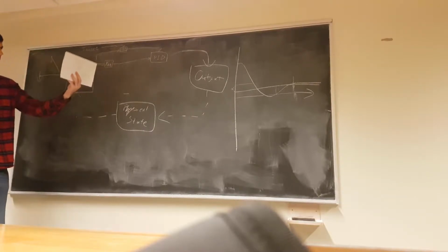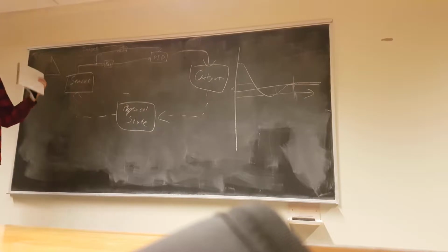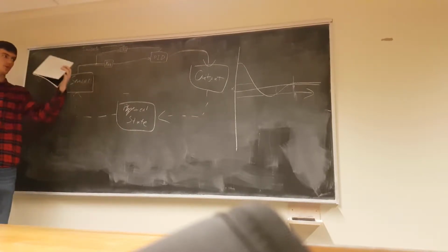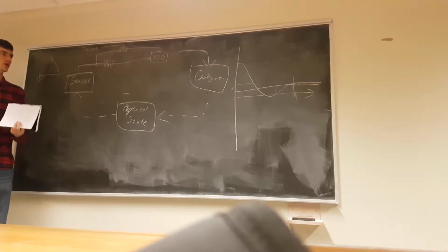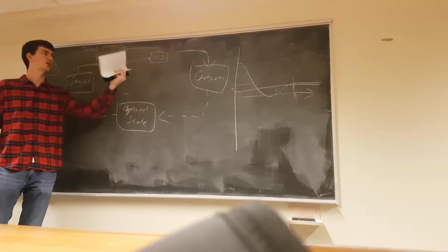Now, another almost philosophical question about this: what is the purpose of the derivative block here in the context of this whole control system? I would say it converts the raw data from the sensor, or whatever input we're getting, into the quantity that we're actually trying to control, which is velocity.